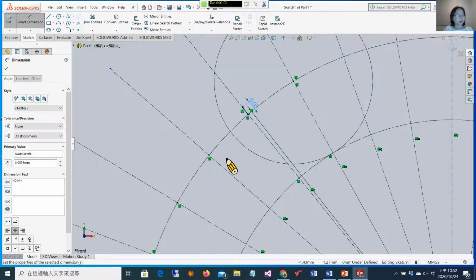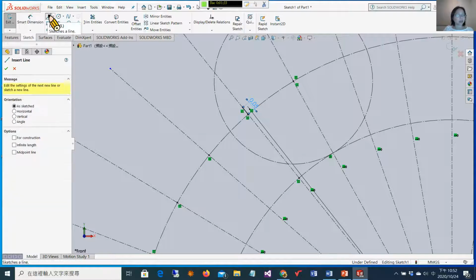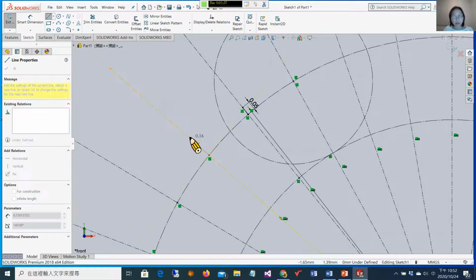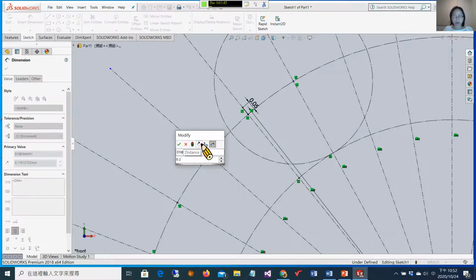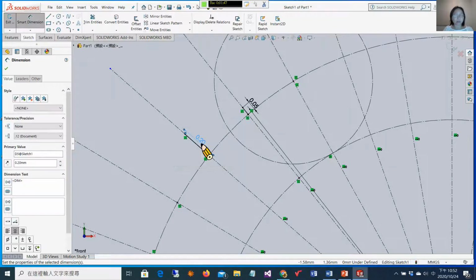Let me see the cam angle 114 degrees. We have the displacement equal to 0.2 inch. So I draw a line segment from here to here and give it length 0.2 inch. So I get this end point.